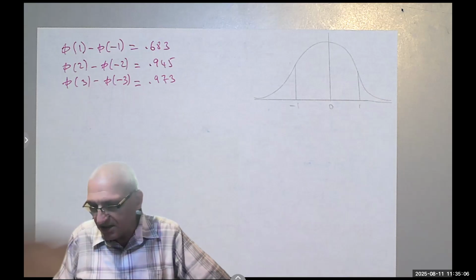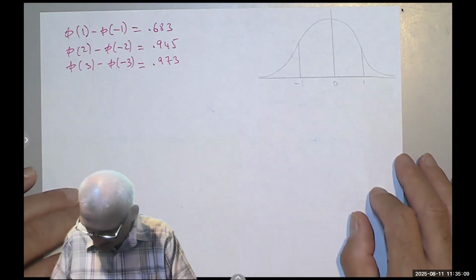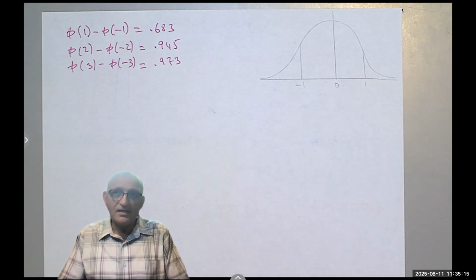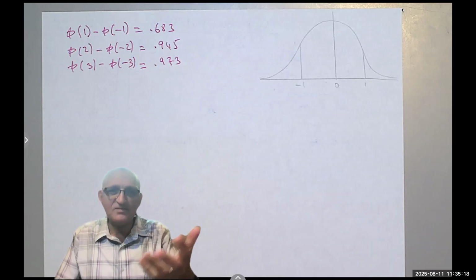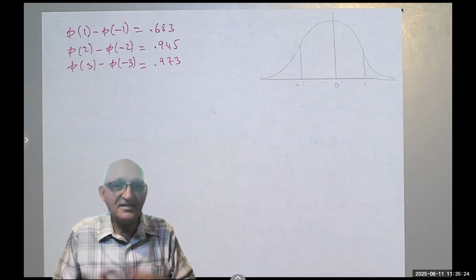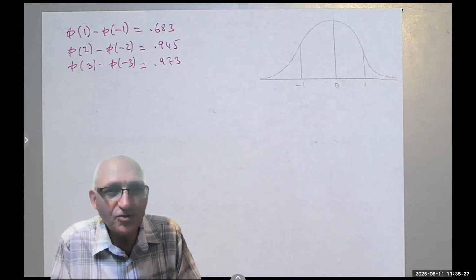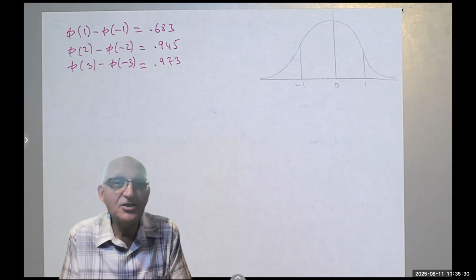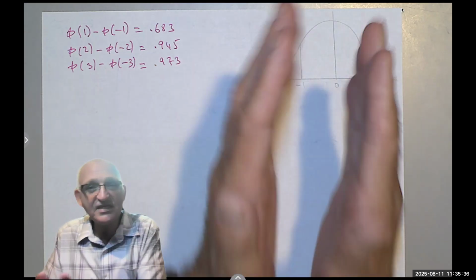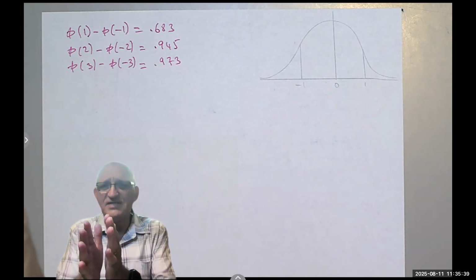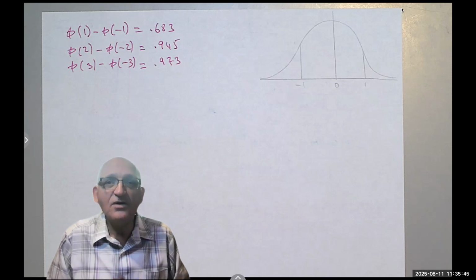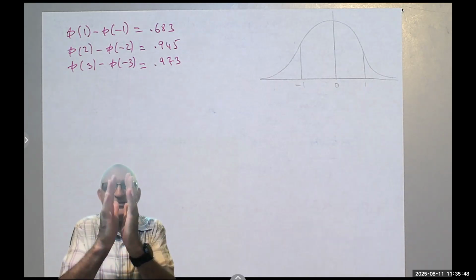You might have heard me talking about an initiative that started by Motorola and then GE adopted it, which is called the Six Sigma. That's hard to explain now, but if you work in quality control, your most ardent enemy is sigma. You want to reduce sigma as much as you can. So they would say, okay, if I have specification limits, meaning my customer will not accept anything outside of this range, I want this range to equal 6 sigma of the process. My process should be very close to the mean.